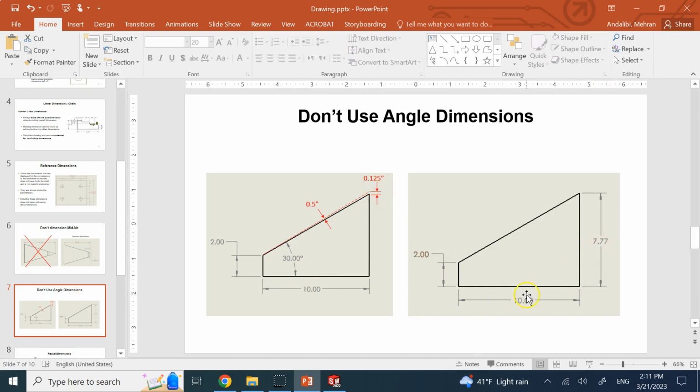So most of the time, linear dimensions are easier to measure and easier to control, as opposed to angular dimensions. You can always hit much, much tighter tolerances with linear dimensions, but measuring angular dimensions and going into tight tolerances for angles is not as easy, okay?